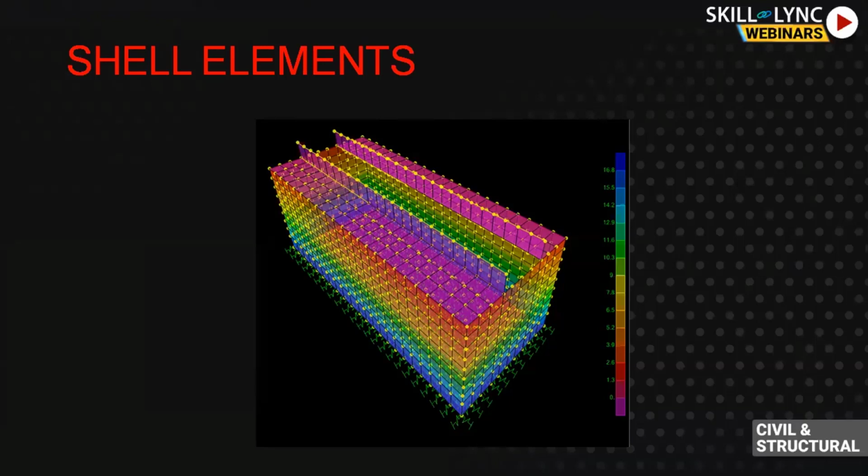The plate element can only sustain loads which are out of its plane. If something is in plane, it cannot sustain it; it has zero stiffness in that direction. Because the tank will have bending in itself, it needs to work like a plate. Shell is the one that has the properties of a plate.